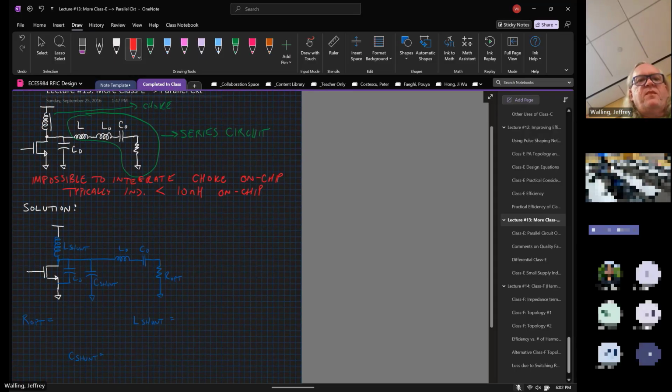What's your definition for choke? Is it 10 times greater than the load, or 100 times? We typically say that when the impedance is 100 ohms or something like that, it can probably be considered a choke. Obviously, it depends upon what's around it, but remember, looking down towards the PA, we have an optimum termination impedance on the order of a couple of ohms. So if that's a few hundred ohms, then the signal is going to want to go in one direction and not in that direction.